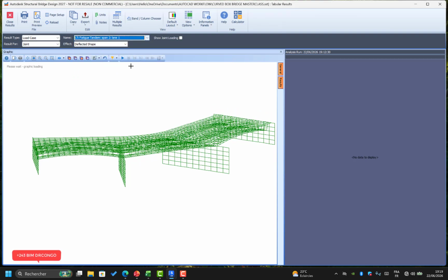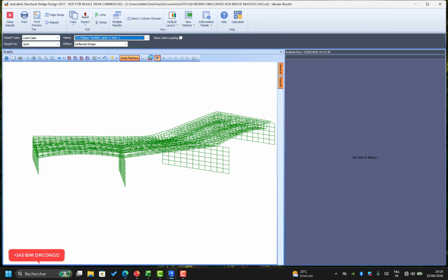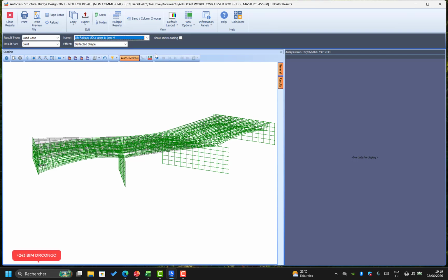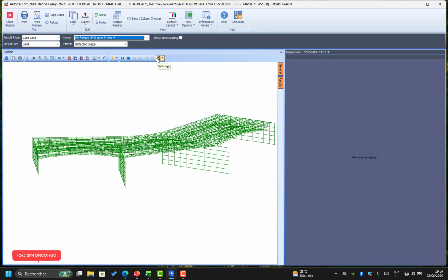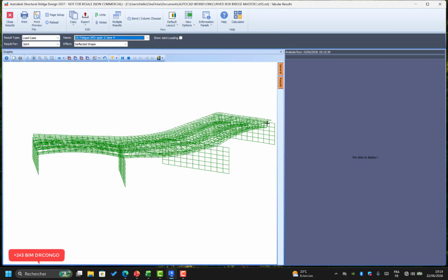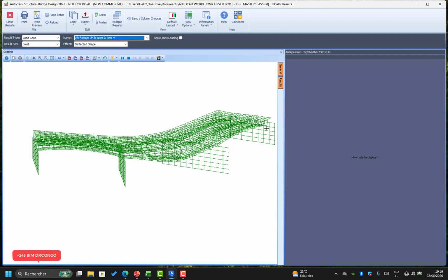instability. So we can change again for line 3. You can see there is another one. You can see line 4. You can see the consequences of instability. The LM3 here, you can see that is the real problem. You can see here for the half lorry, the deflection and the instability of that one. It all depends on how we make the supporter bearings on the abutment. We did not do it. If we had made it, we could reduce the effect of the instability in the middle of the span.